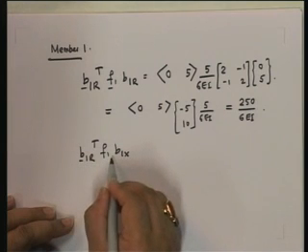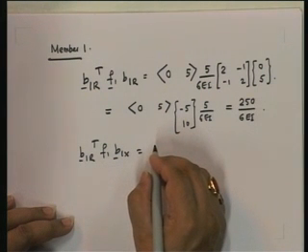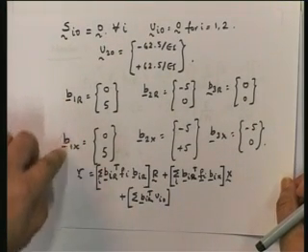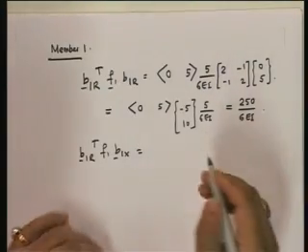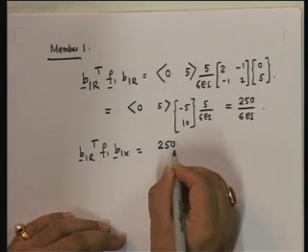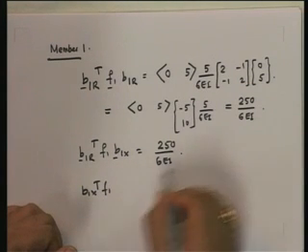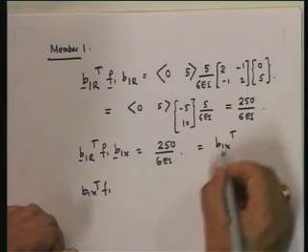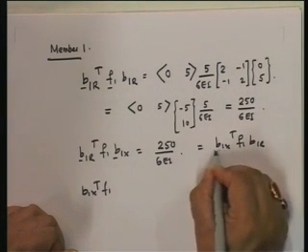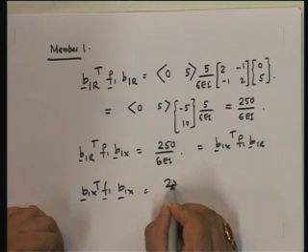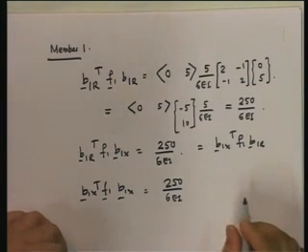So let us look at B1R F1 B1X. You will see that since B1R and B1X are identical, both will give you identical results. So you're going to have 250 upon 6EI for B1X. This incidentally is equal to B1X transpose F1 B1R. Satisfy yourself that that is indeed the case, and B1X is also 250 upon 6EI. So I have found that out for member 1.